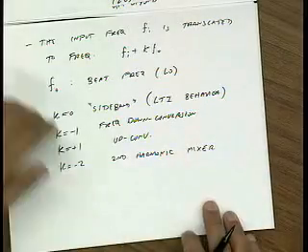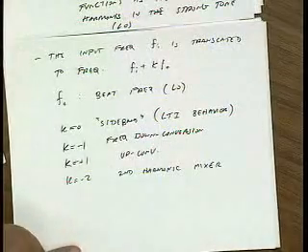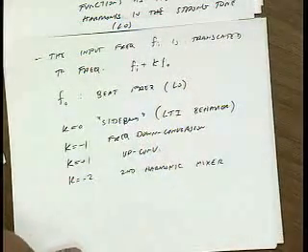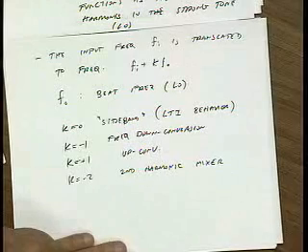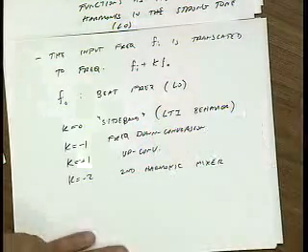And so when we do our PAC analysis, we have to tell it which sideband we care about. Okay? And then that's it. It's just like doing regular AC analysis. You supply your input frequency and the sideband, and then you plot the output frequency.